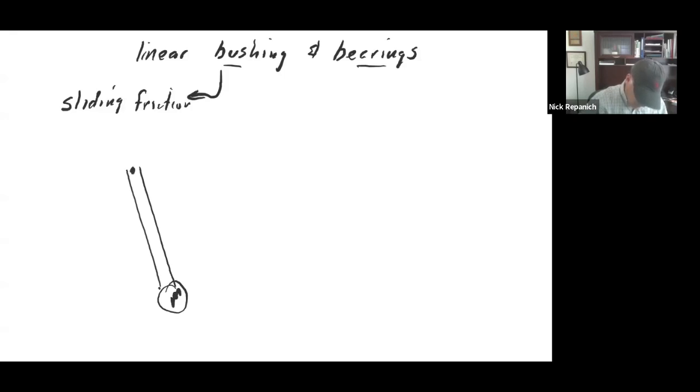This point right here is really easy to make go in an arc some distance, right? But to have this point actually move in a straight line over to this point means you're going to need an extra pivot point, and you're going to need some combination of two different motors moving together to actually get straight line motion.